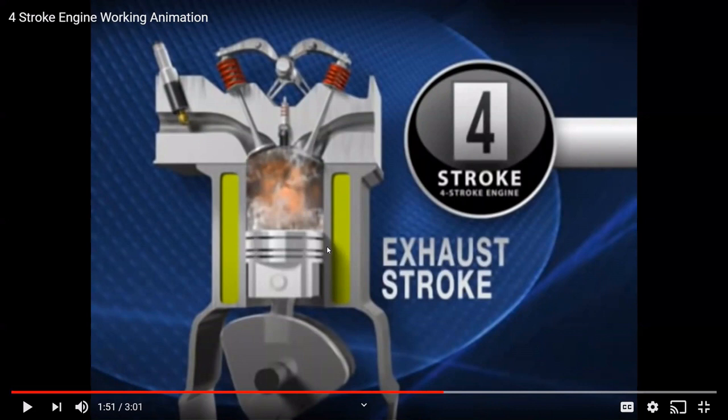And that means the volume didn't change. You get that? So the exhaust stroke and intake stroke are just kind of deleted from the time lapse of this whole process and approximated as an isochoric dumping of heat to the outside and a return to initial temperature and initial pressure. Okay, I think now we should look at the cutaway slow motion video.